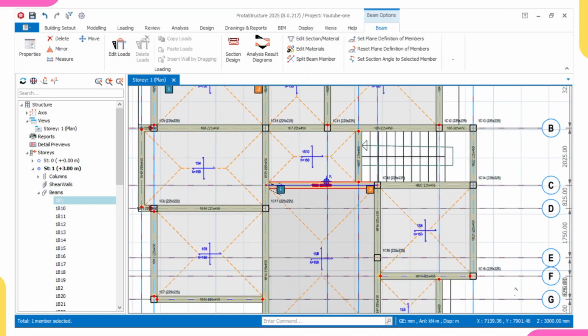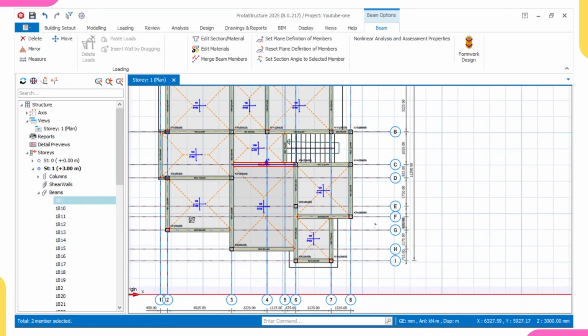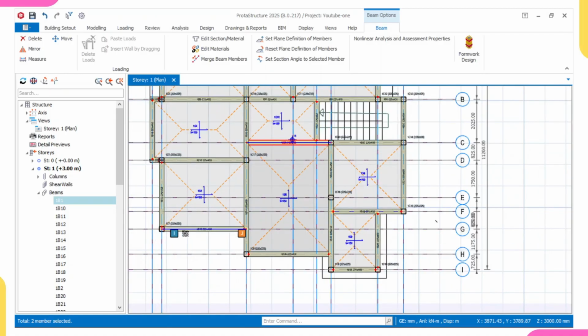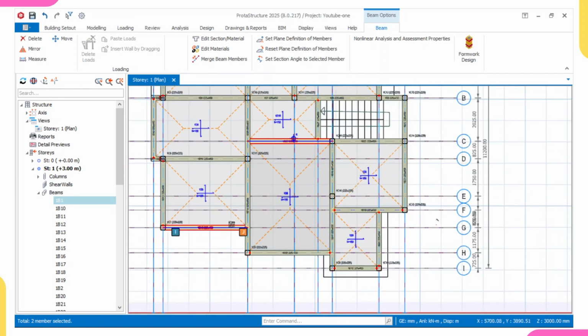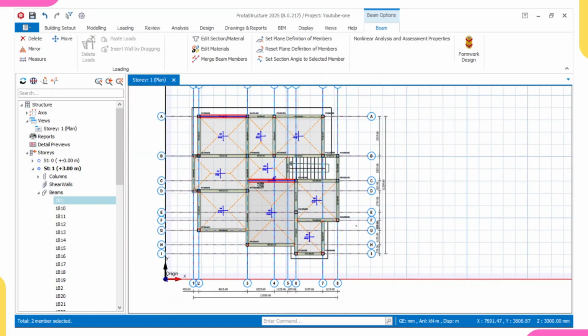So this one I'll hinge. This one is I, but I will not hinge it because we're having a cantilever. This one is I, but remember we have already done this as a simply supported beam, so I will not hinge it again. If you hinge it again in form of I, that means it will only hinge here. The one you did for both ends will be undone, and then only here will be done. So I will leave it. I have done this. Then I have selected this.